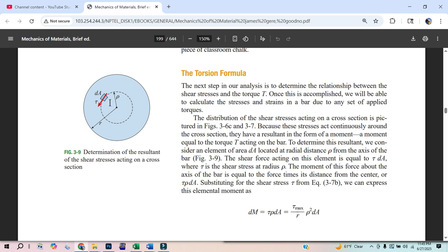So I like to use the saying, radians times radius is something normal. I say that first, and then I say radians times radius is arc length. And it's useful because radians per second times radius is tangential velocity, and angular acceleration, radians per second squared times radius, is tangential acceleration. So this whole idea of radians times radius is something normal, I think is a very useful phrase. That's the way I remember it.